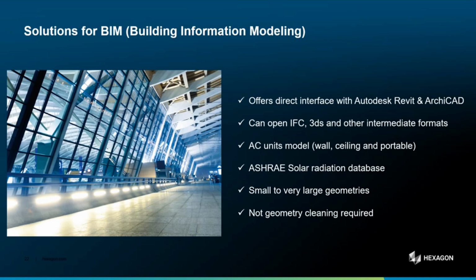So, for example, directly importing the geometries out of architecture solutions. We are talking about Autodesk Revit, ArchiCAD. So definitely they are not using CATIA or SolidWorks to design the buildings. So we are also able to import directly their geometries. And again, we don't ask them to refine the geometry because there is nothing more dirty than a building geometry. I don't know if you already have a look at this, but this is really dirty. So that's a good point. You don't have to waste your time on that.